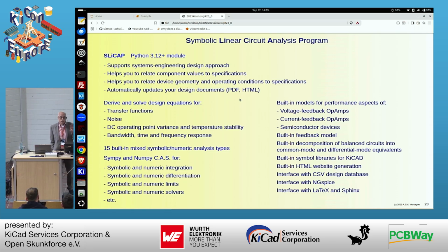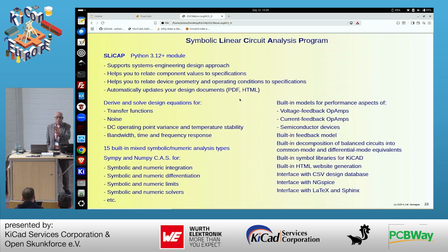Now look at the feedback amplifier. You have a controller, which we call op-amp in our daily work, but the function is just a controller, and you have a feedback network. They both contribute noise. So if you want to design them independently, you have to give them a budget. If my amplifier should have a budget of 3 dB for noise figure, I say, okay, let's do 1 dB for the feedback network and 2 dB for the controller.